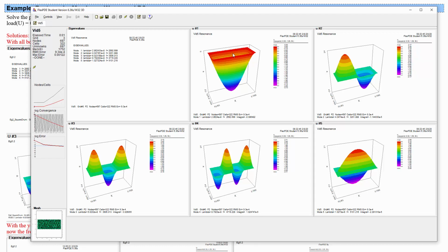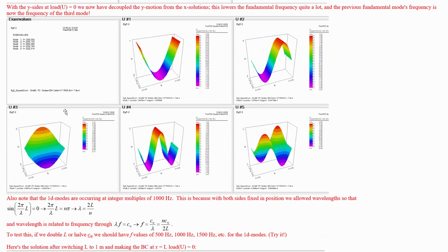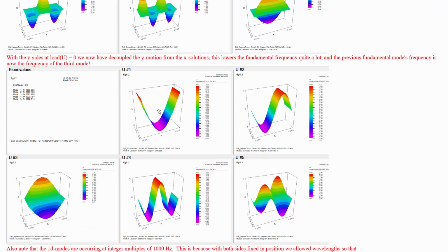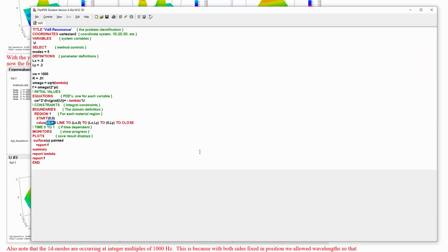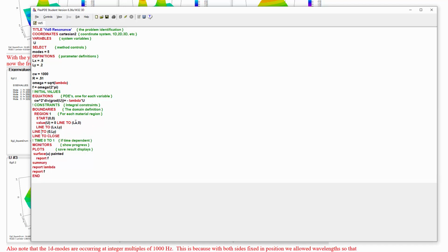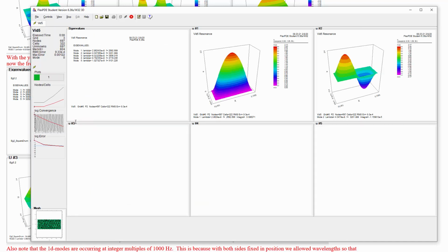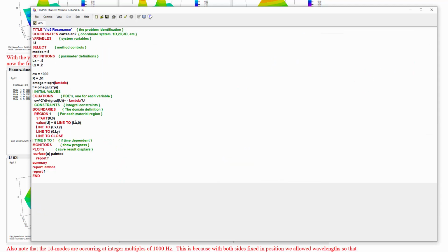We can go to adding load boundary conditions on these sides. That's the next one. So imagine if we have load boundary condition on the extreme sides in Y. How are we going to do that? Well, we're going to need to separate this out. So first, let's draw the separate lines explicitly rather than saying 2 and continuing the same line. Let's just draw it as separate lines. Shouldn't change anything. All good.